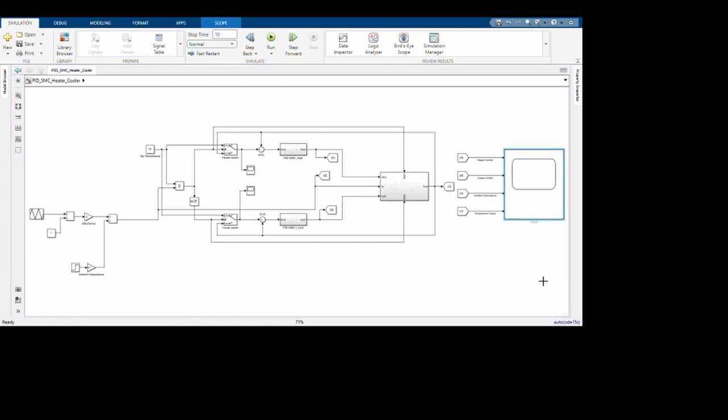If we were to model this into a second or third order differential equation, that would be more accurate, more robust, but more difficult to control. But this is the simple know-how of how real world systems can be put into mathematical equations and controlled in different ways. So now that we've established that a gain of 3 is very easily handleable, let's give it something very extreme, like 10.